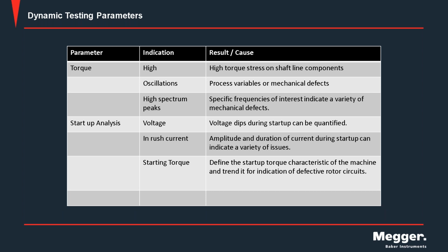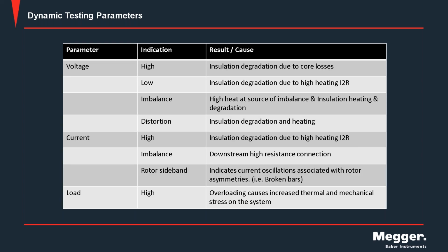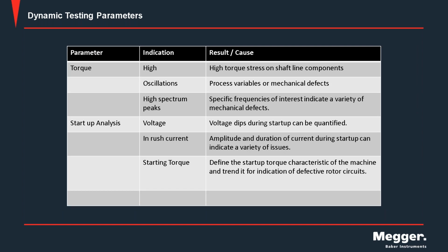And loading's not the only thing that creates the heat, right? If I have an under voltage condition, an imbalance condition, high distortion, I can have all three of those things, and I could be overloading the motor as well. So really quantifying each of those, where the low hanging fruit is for getting those things remedied, gets defined when we look at dynamic data.